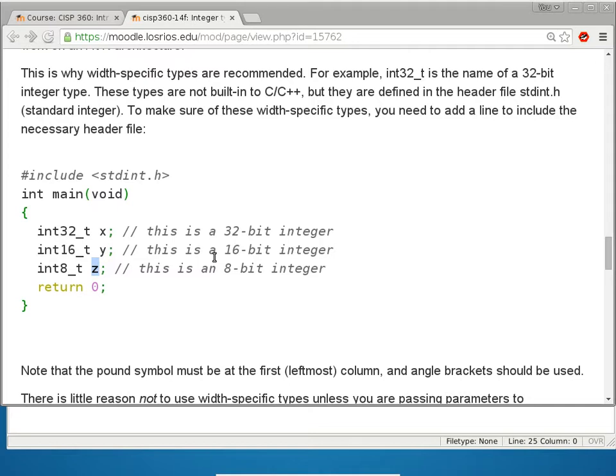Okay. Well, the answer to that question is it depends. But what it depends on is the architecture. In other words, if you have a 32-bit architecture like the Intel processor, it means it can perform a 32 by 32 addition or subtraction in one single clock cycle. Making it a 16-bit or 8-bit operation does not speed it up.